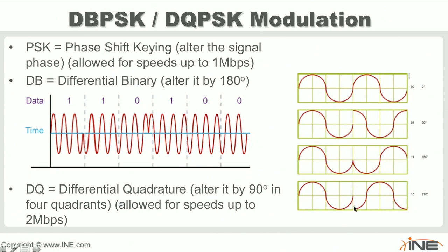If I were to cut this bottom piece here that I have my arrow going around, hopefully you can see that well, if I were to cut those 8 boxes out and take this single hertz or single cycle and lay it over top of this waveform here, it would be 270 degrees out of phase. It's basically the same as 90 degrees out of phase, but it's negative 90 degrees out of phase, if you want to call it that. It would be the same thing.